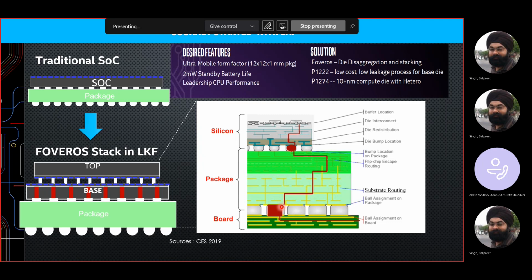because the bump technology today, the package side bump technology, the transformation is not that fast. Today, the best bump technology in the market is probably about 90, 100 micron that you can get. The little bit cheaper technology is 200, 250 kind of stuff. So that's the unique challenge it forces. But is it not a solvable problem? Yes, it is a solvable problem. When you create more parallel paths, you take extra metal layers and start to solve that problem. So these are the things you have to articulate when you plan your design. Otherwise, you will see a backfire down the line.